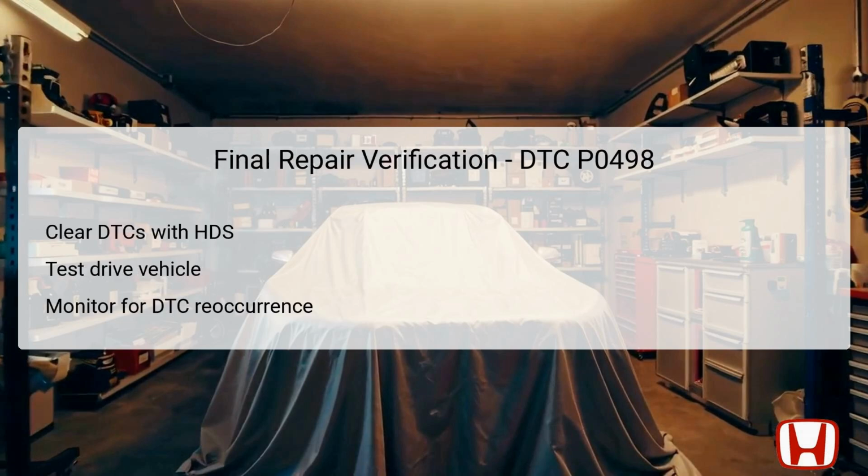After completing all troubleshooting steps for DTC P0498, it is crucial to conduct a final repair verification process. Start by clearing any DTCs present using the Honda Diagnostic System, HDS, to reset the vehicle's onboard diagnostic system. Following this, conduct a test drive of the vehicle under varied driving conditions to ensure the repair was successful and the system is now functioning correctly.